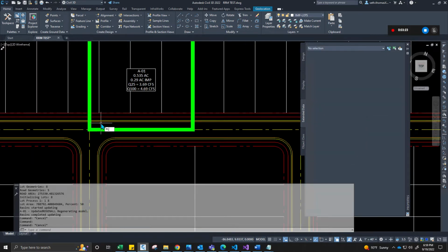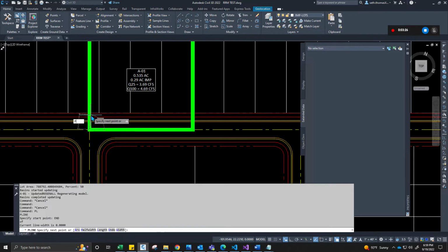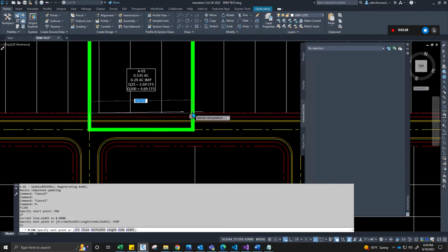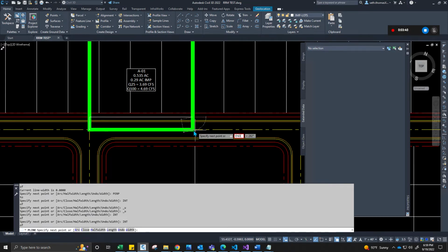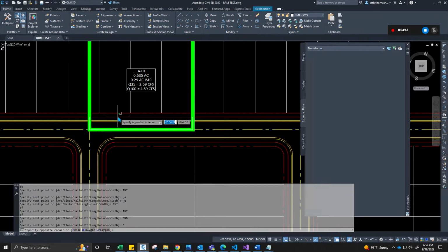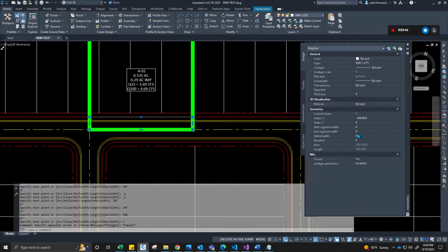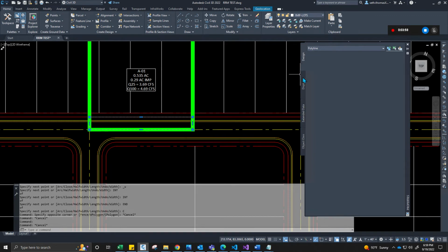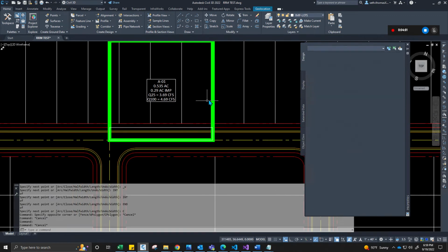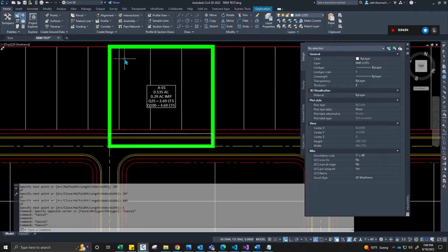And just to confirm, we'll measure it all out. We see that our road coverage, whoops, I went a little too far there. Our road coverage, I have this area as 2,952, and let's see what we got here. We got 2,953. Let's see what our rounded error was. So yeah, 0.69. So we got our impervious cover for our roads correct.